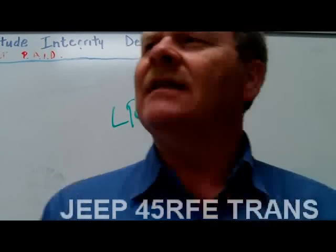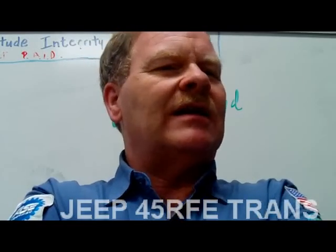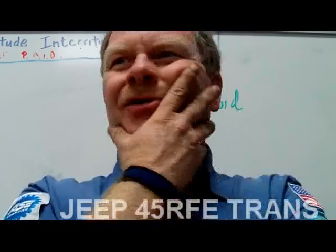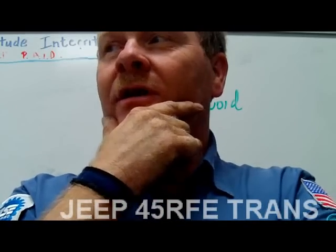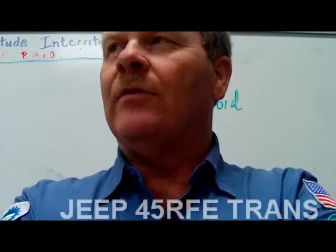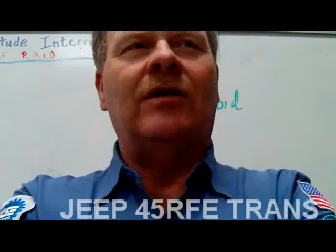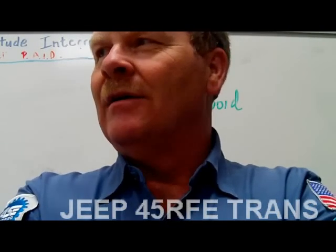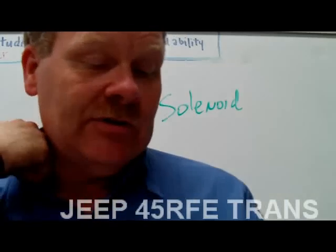Let's say you're looking at your scan tool and you're saying, well, my coolant is not that hot, but it has kicked the fan on. Why would it turn on the fan? And then you look and you notice your transmission temperature. You've been sitting here in reverse or in drive a long time, and it's up to 240 degrees, and you hear the fan kick on, even though the engine may be running at 190. You say, it's not supposed to come on. So there's a lot of stuff our computer's doing that you need to know about.